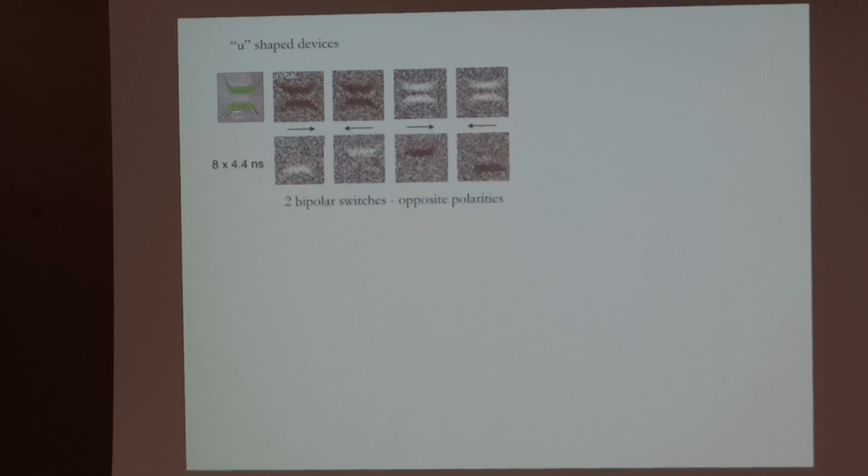So what about the experiments? We made these structures, and here you have the SEM image and the differential curve imaging showing the initial states of the magnetization before we excite with current. You can see that after applying current pulses, positive current switches one of the objects, negative current switches the other object. It is the opposite case when you change the initial state. So this is perfect bipolar switching.